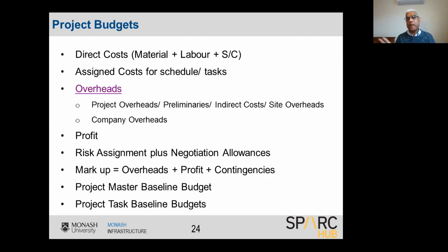No, that's not the way. Because that project may be $50,000, whereas you might have a project with $200,000. So you prorata the company overheads and put that cost on top of the direct cost, and then the project overheads. They are the project staff, site overheads, and then a fraction of the company. So that's how your budgets are prepared. And then on top of that, you add your profit and the risk. That's how the budgets are prepared.